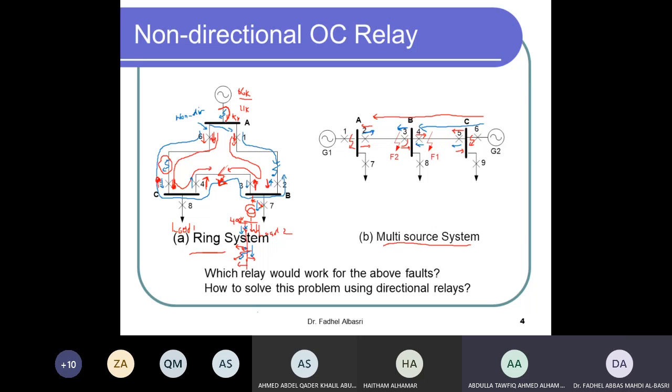Yes. Won't change the fault, because from this load we don't have any generation. Okay. I don't have any generation. These are radial system loads. Right. So those won't supply current backward. So when I have current here, only current goes from this direction. There will be no current reversing. So even if I have a breaker here, okay, I don't need this breaker to be directional because always current will be in this direction. There will be no current reverse from the other side, from the load side.